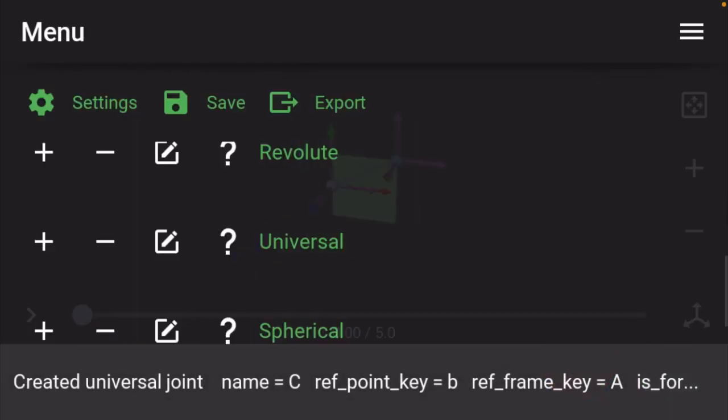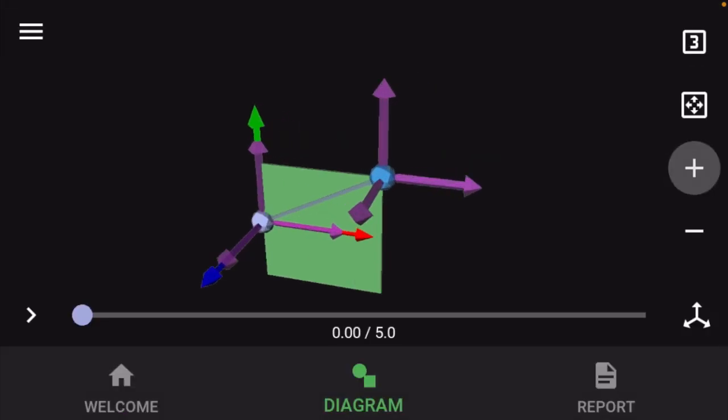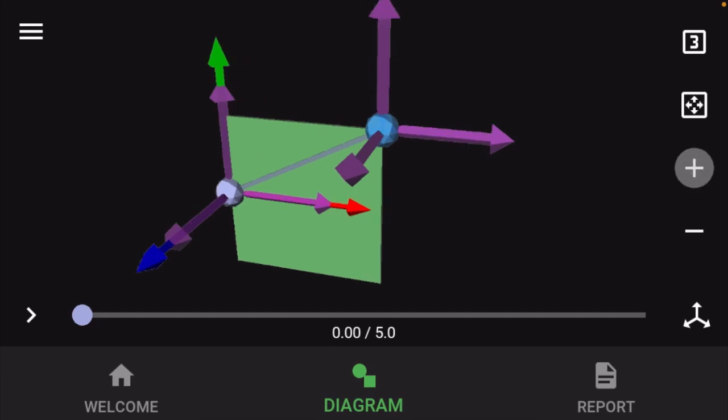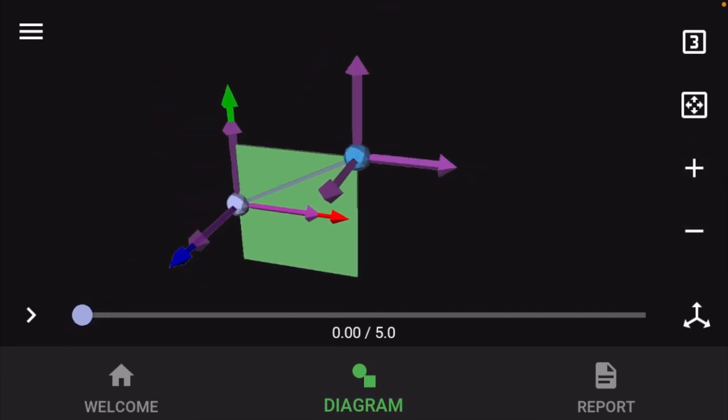So this second panel, or what's going to be the second panel when I create it, is carrying a little bit less total mass and inertia. So I'm actually going to assign a little bit lower stiffness as well. So we can see the second joint that's been created.